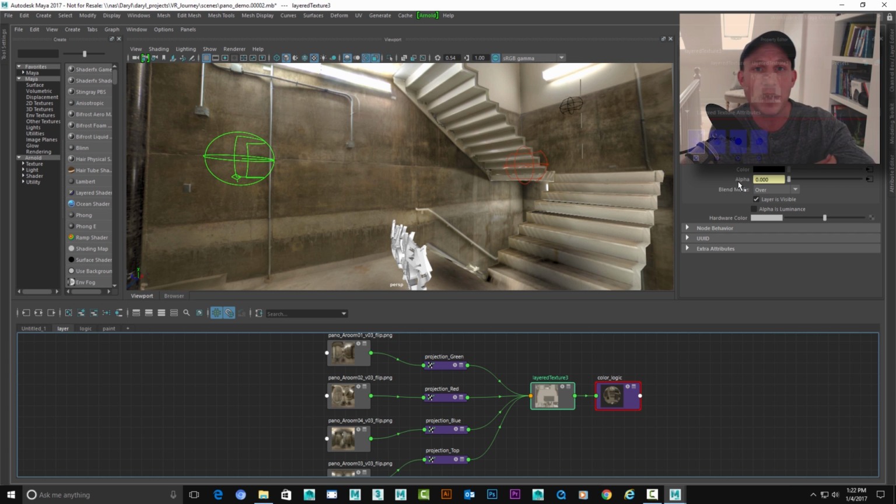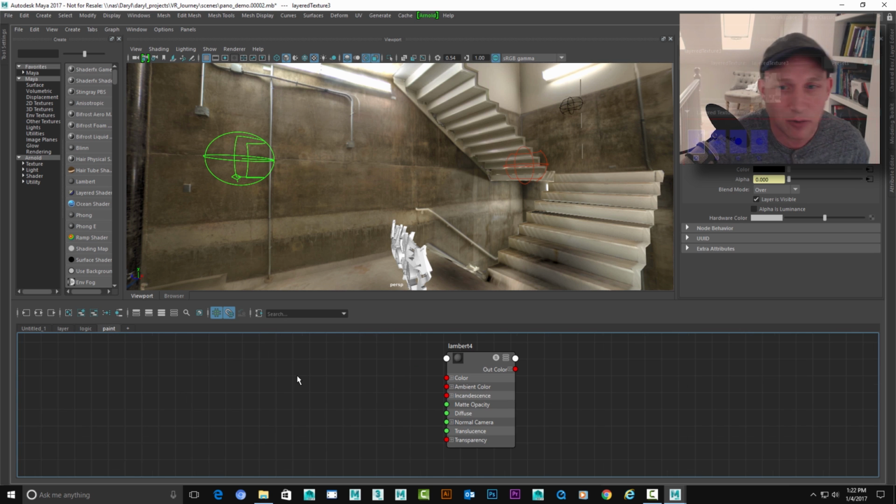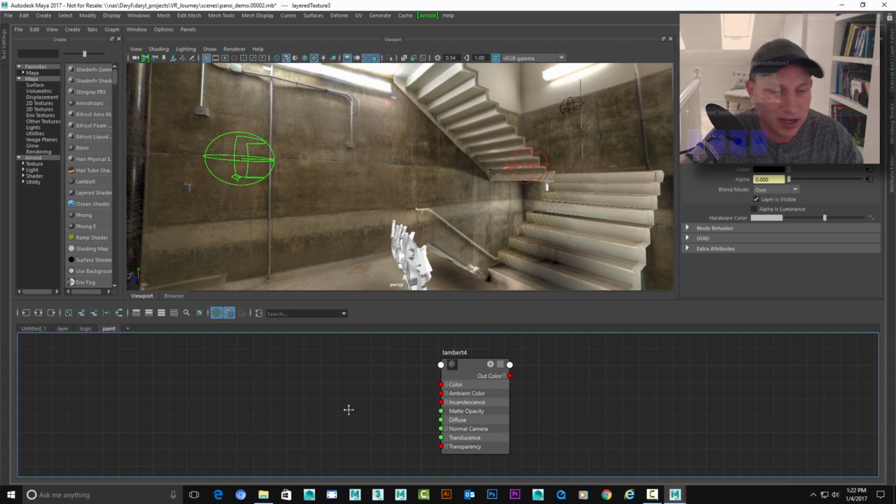So how do you handle making those alpha channels? Well, I like to use texture maps to do that. And I actually like to paint a red, green, and blue file because that gives me the ability to get pure masks, 3 different masks as well as like a 4th mask where there would be no color. And it gives me one easy mechanism to generate where these textures are going to be applied. So how do you do that?